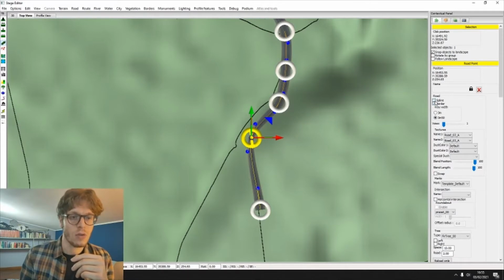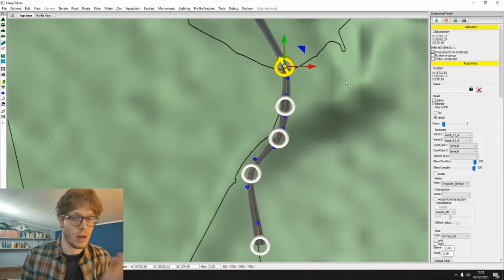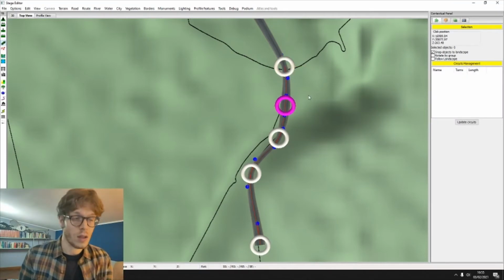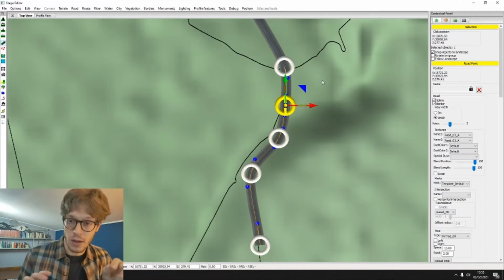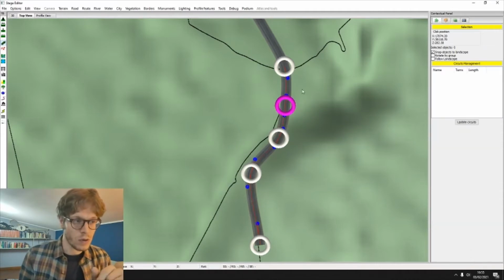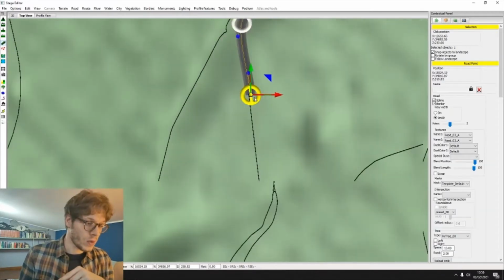So we reselect. We can do also spline. If I unselect spline now, I can change some points. So I have a road that is a bit narrower, a bit larger. But if I want to reset and transform all the road the same way again, I select spline, and then I re-click on 2. This is because, for everything, this is an example, but if you want to edit just one point, you have to unselect spline. If you want to edit all the road, you select spline. So we continue tracking the road.